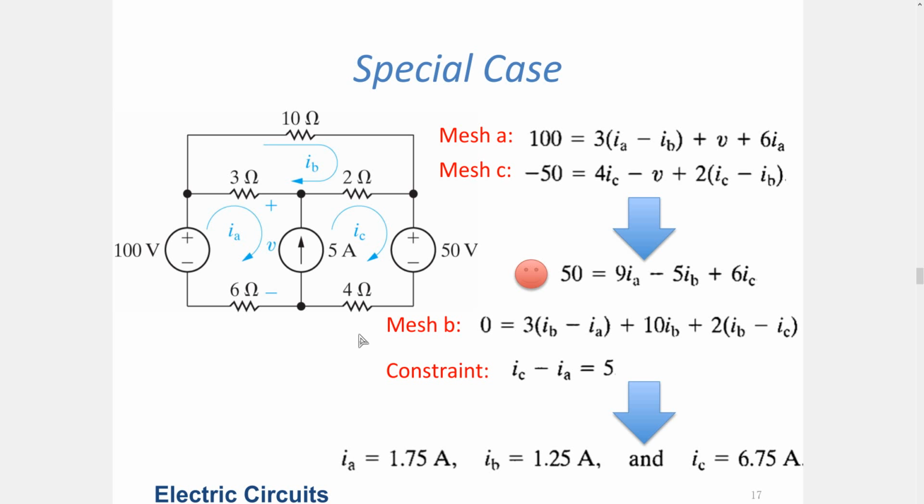When we compare these, the node voltages versus the mesh currents, node voltages is more universal, because you can always measure the voltage, as the voltmeter is ideally an infinite resistance component.